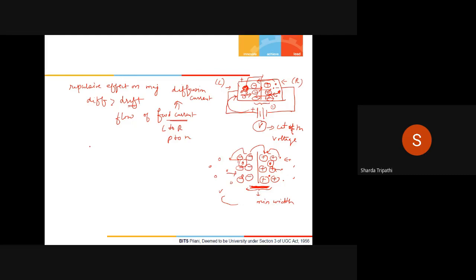So now, again, to sum everything up, in the reverse bias region, we had only small current, which was due to the presence of minority carriers. We called that the reverse saturation current, whereas in the forward region, you will have some actual current flowing through the diode, and this is known as the forward current. The difference is that reverse saturation current was drift current, whereas the forward current is a diffusion current.